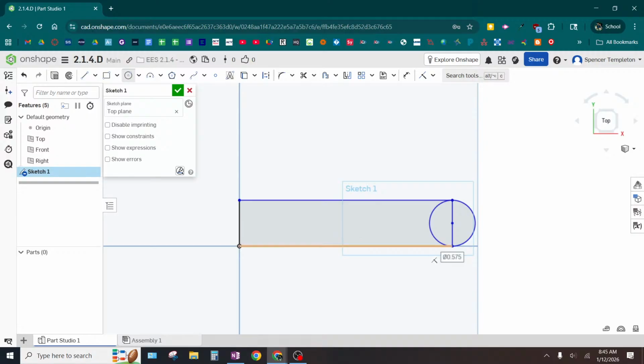That's a way to do a curve. It's not the only way, but it's a very fast way. This is like when I drew two rectangles on top of each other to make that L shape, or that T shape rather, last time. You can use the scissors tool, the trim tool right here. I could trim away the parts that I don't want or need. Okay. That's an option. You could also use the arc tool. So I could draw using the line tool.